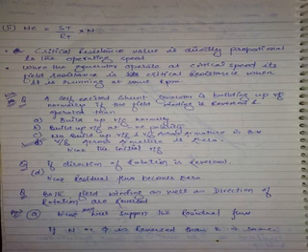Now, if you reverse the direction of rotation, what happens? Previously you had clockwise, and the current came like this. Now the polarity of the induced voltage is reversed, definitely. So the current will not come like this. Previously this was plus and this was minus; now this is plus and this is minus, so the current flows the other way. It will neutralize the residual flux, so no build-up. The polarity of induced EMF depends on the direction of rotation.